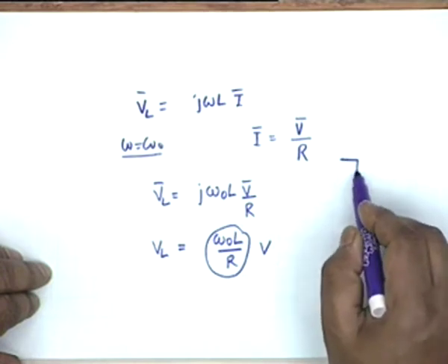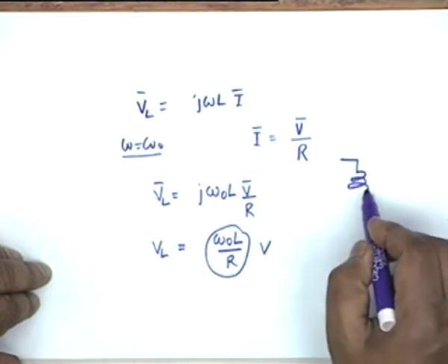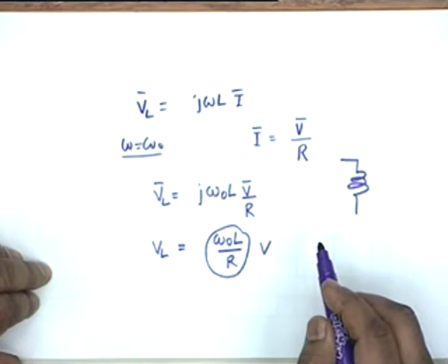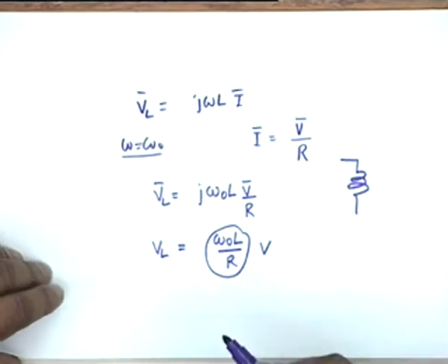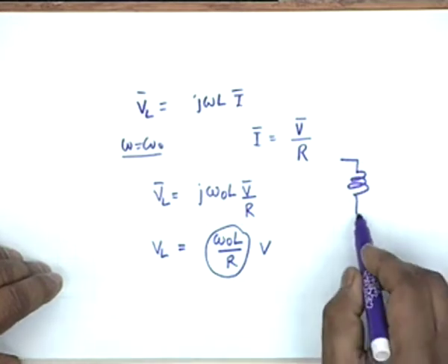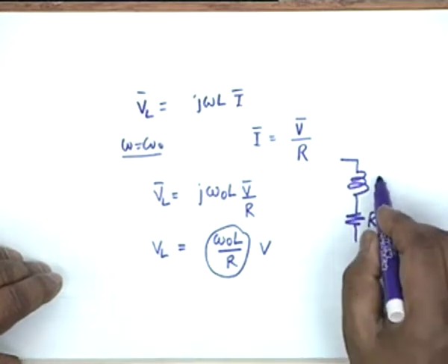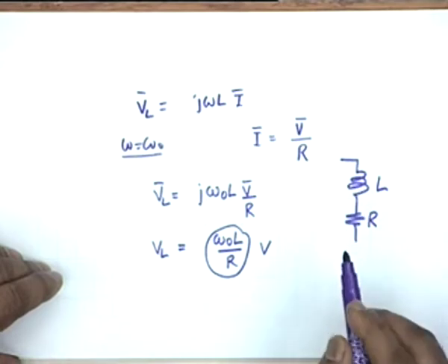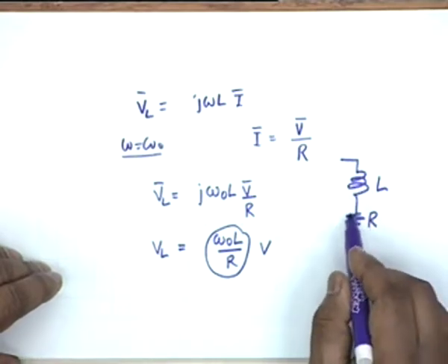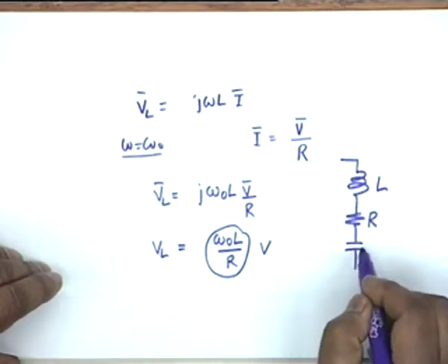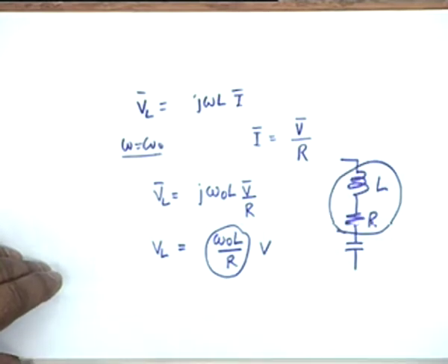Suppose we had no resistance in this circuit, suppose the resistance was 0. The resistance that we are talking of basically belongs to the inductance. You cannot make an inductance without a wire, and a physical wire shall always have a resistance, and therefore this resistance that we show usually is the resistance of the coil, or this resistance determines the merit of the coil.